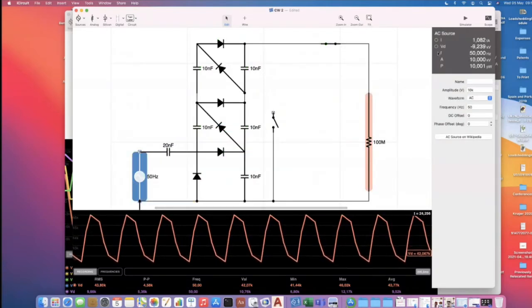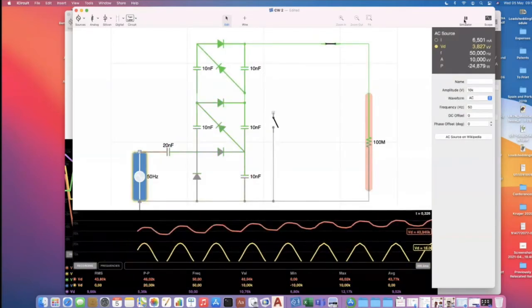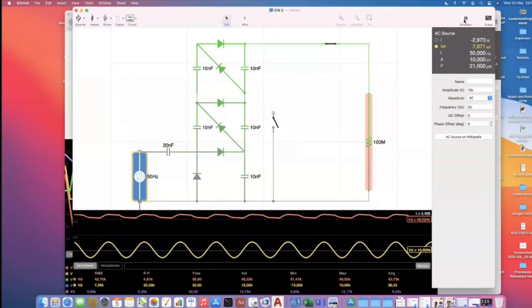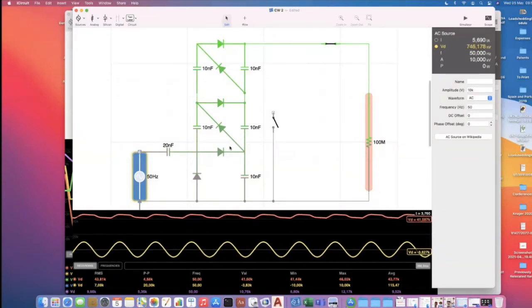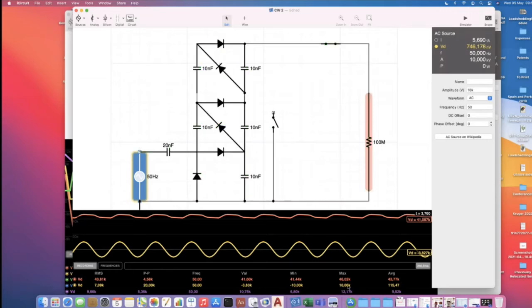Let's put the AC waveform in. Right, so in this case, we've got a 3-stage generator. For our ideal case, it would be 3 times 2 Vmax, so if our Vmax is 10 kV, we would have a 60 kV perfect waveform at the top there.